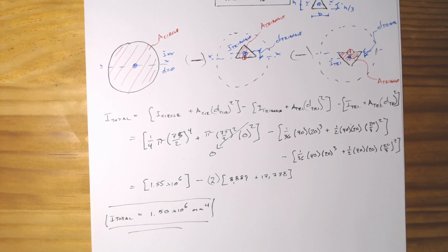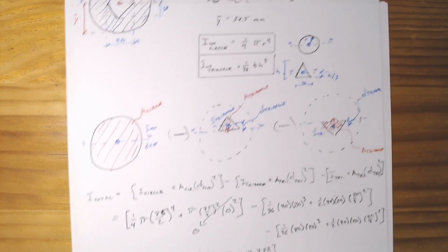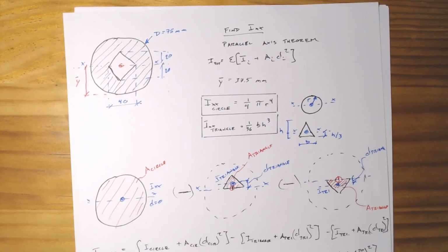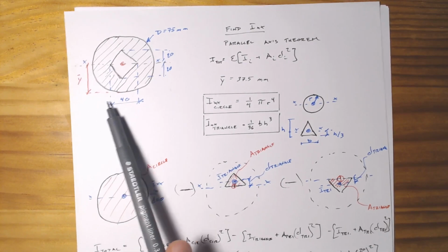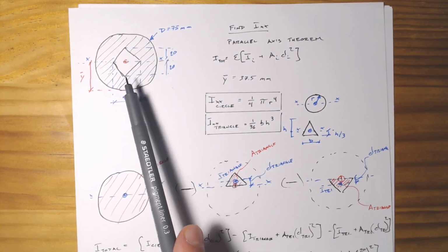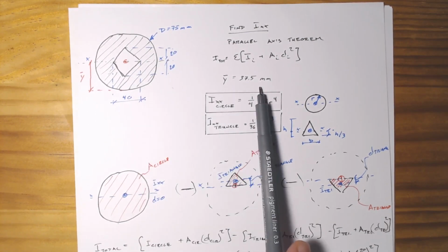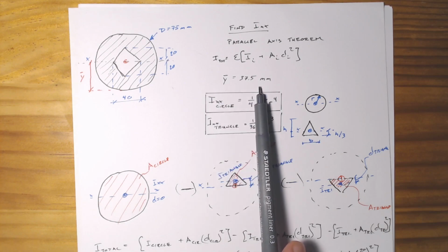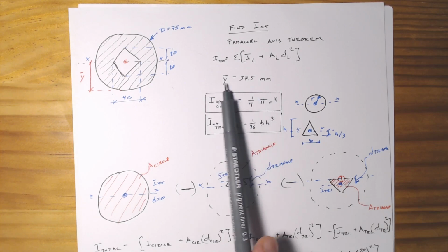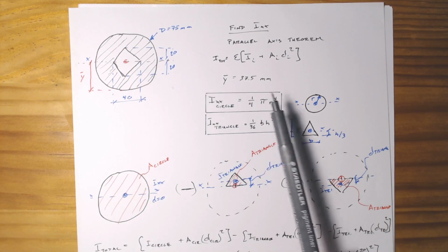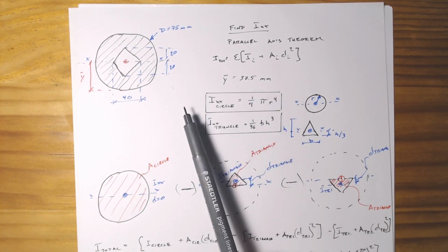So again, very similar to any of the other parallel axis theorem equations that we've done, where for a complex section like this, where we've got an external and a centroid, we first work out the location of our centroid. And so for going about the x-axis, that's determining y bar.